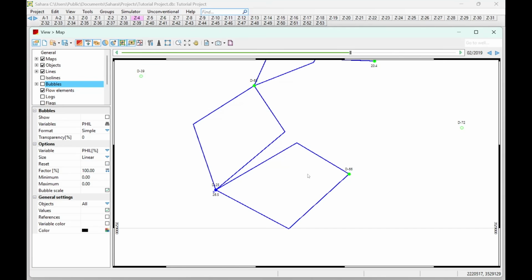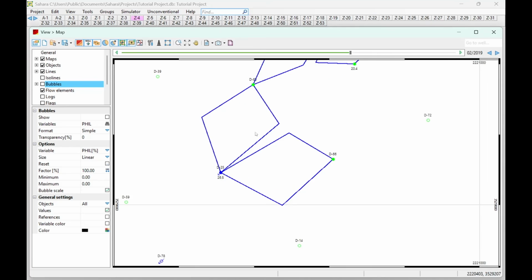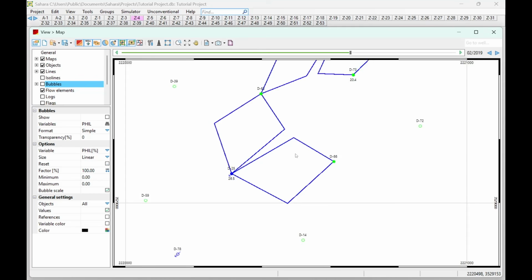So in that way we can represent the leakage of the system, that not all the water that is being injected is being utilized properly for secondary recovery. Some of it might be lost to the system, so that might be considered as well. So the idea is to have a distribution coefficient associated to each different flow element, that is going to explain the relationship between the total water injected and how much is actually affecting the producers nearby, and how that water is distributed between the different producers.